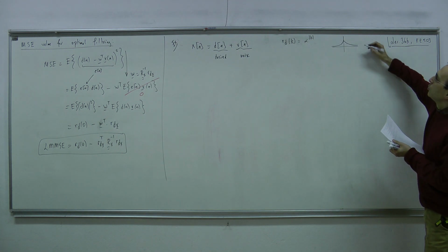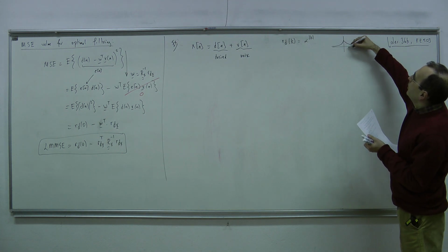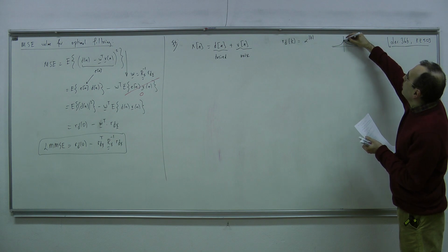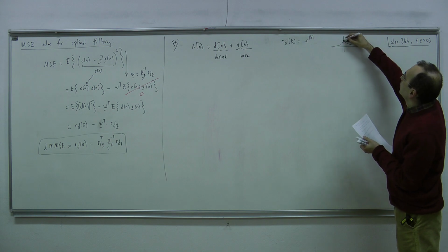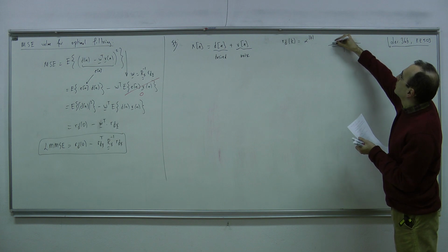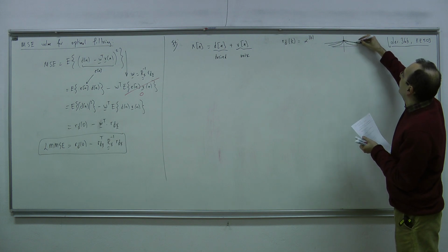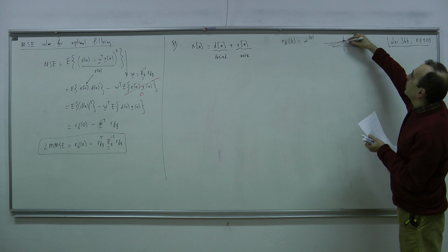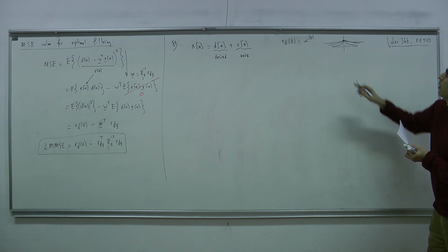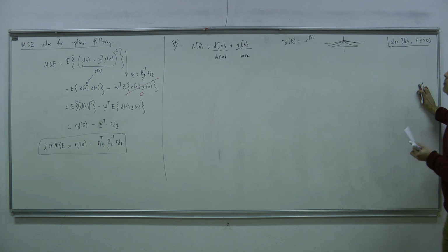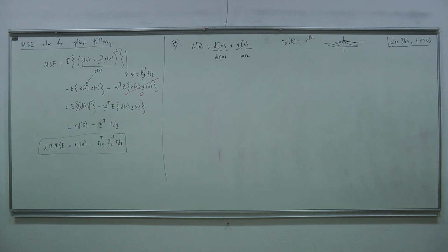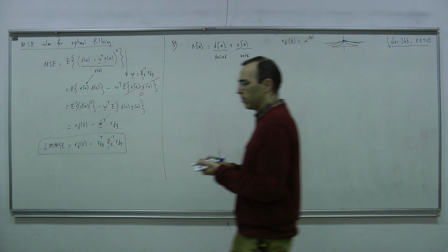Autocorrelation shows the linear dependence between the samples. If I make it decay much slower, meaning that alpha is closer to 1, then my samples are more and more correlated as alpha gets closer to 1. So I see an exponential correlation.